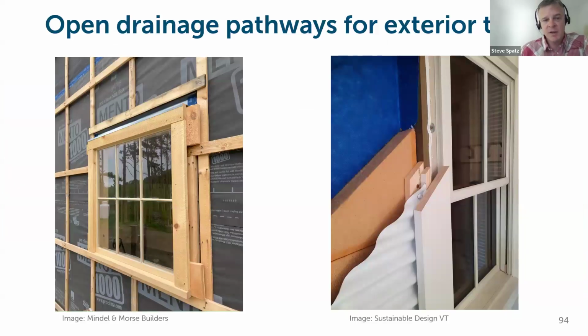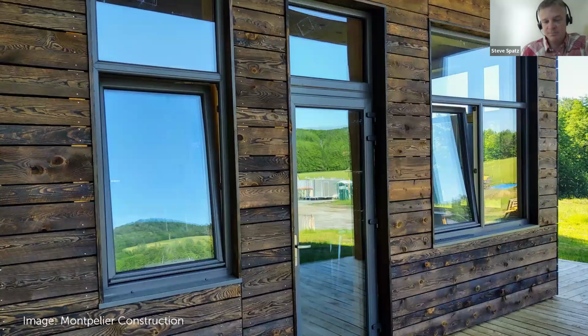So looking at new ways of putting your exterior finishes up that doesn't rely on trying to keep the water out necessarily, but just effectively understands that if water does get behind them or does get in from the exterior, it can just freely and easily drain out, dissipate, or diffuse to dry.